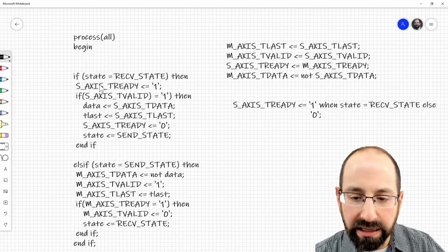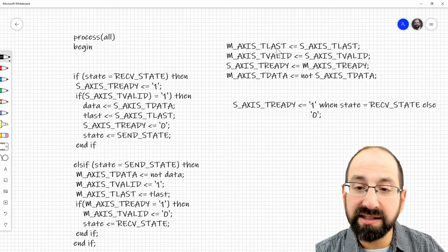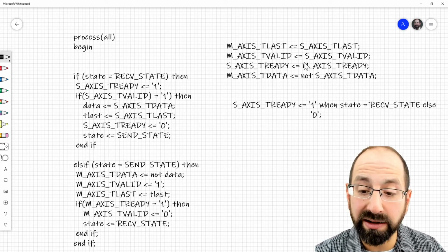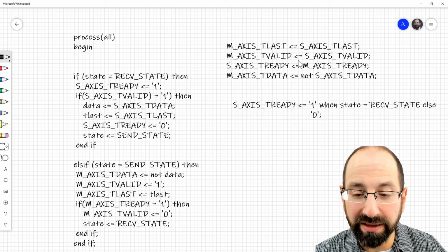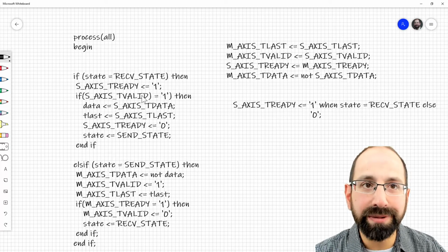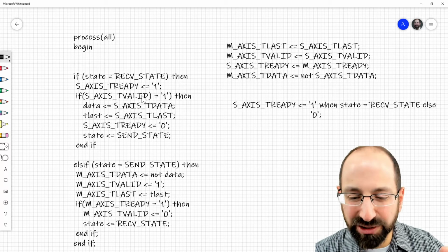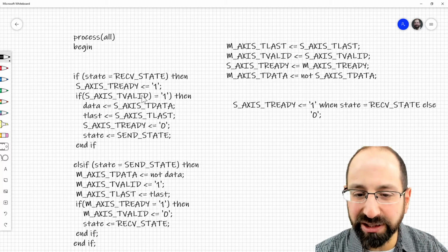Performance-wise, there's a bit of a trade-off between this design and this design. This is just combinational logic, so this is just pure pass-through. That's probably higher performing in the sense that there's no extra clock cycles required for this. This one maybe is getting 50% ideal bandwidth, right? Because it's taking 2 cycles to do that single transaction.